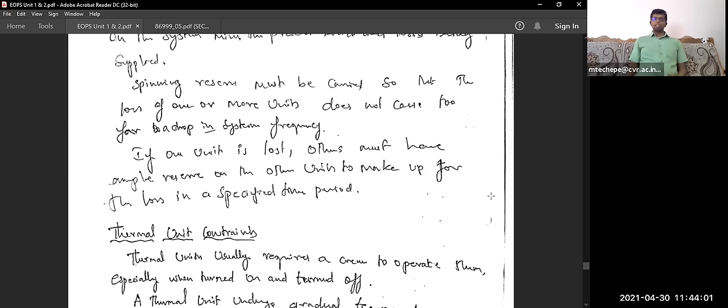Once the unit is ready, some fault might happen in a particular generating unit. So what we do is keep a reserve generator always there, so it is maintained always, with maintenance and operation. Sometimes they go for a spinning reserve generating unit in the generating units, or in the substation only. This will be run for a specific period of time.